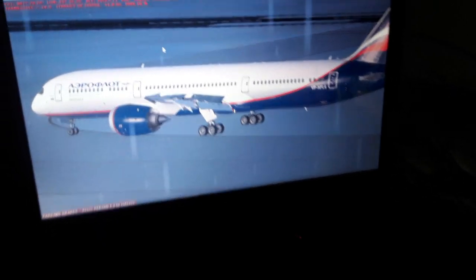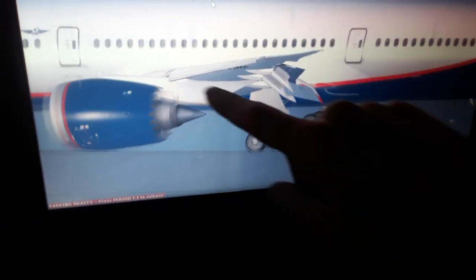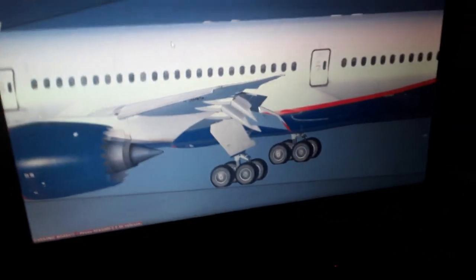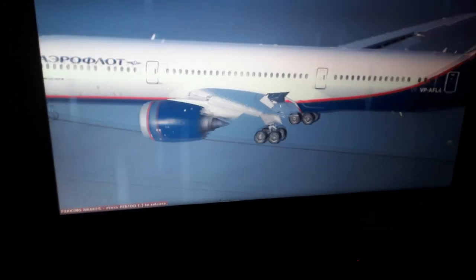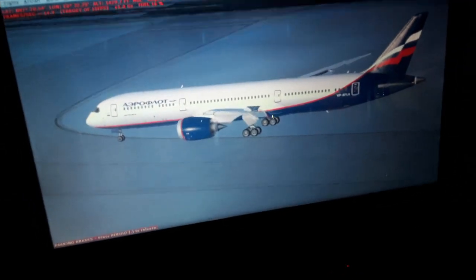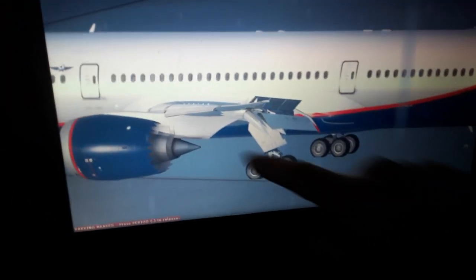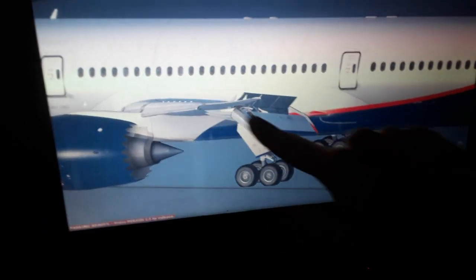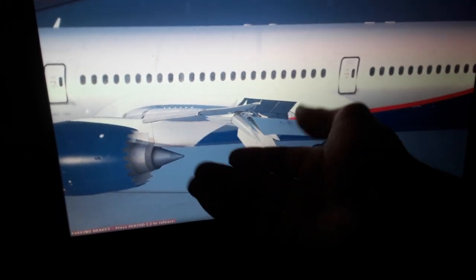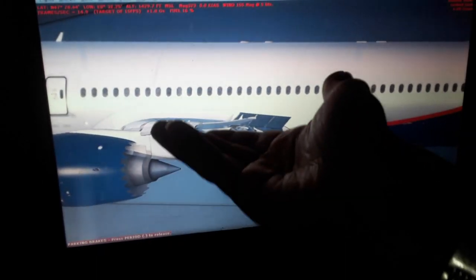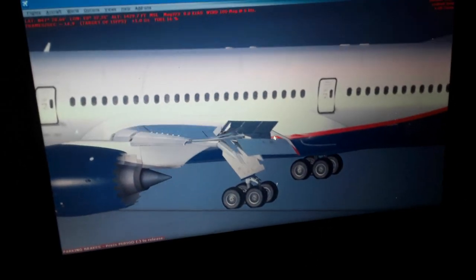You can see the bottom surface of the wings is more flat. Also we have now the flaps extended, and when we fly we might have an angle of attack like this, a positive angle of attack, so the airflow will be moving slower below the wings, so we're going to have higher pressure, which pressurizes the aircraft's wings and lifts the weight up into the air.